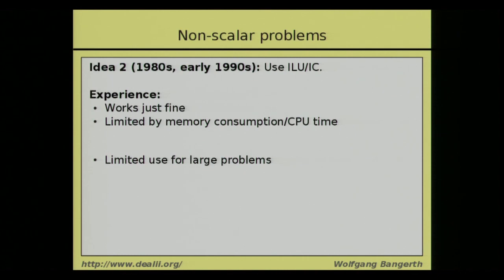The problem is that typically these coupled problems lead to very large problems. So if you have something like a Stokes system with a Q2, Q1 element, then you end up not just with, for example, 5 or 7 or 9 entries per row, but you very quickly get to 100, or in 3D to several hundred entries per row. And as a consequence, computing something like an LU factorization, even an incomplete LU factorization, becomes a very expensive and very memory expensive process too.